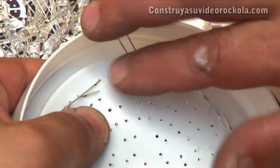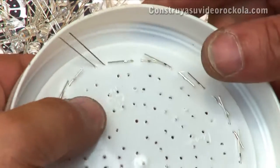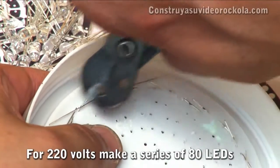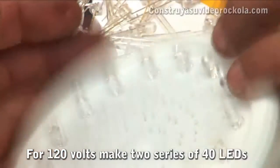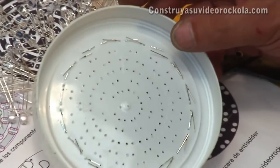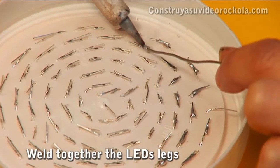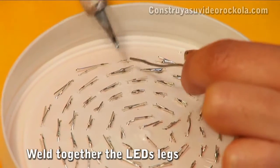At this point, we must adapt the wiring to the voltage to fit our circuit. If in our country we have a mains voltage of 220, we must make a single series from start to finish with the 80 LEDs. But if we have a voltage of 120 volts, we should make two sets of 40 LEDs. Having made the connection of the LEDs, proceed to solder them, joining all the LEDs together. Be careful not to melt the plastic, and make good solder joints quickly.